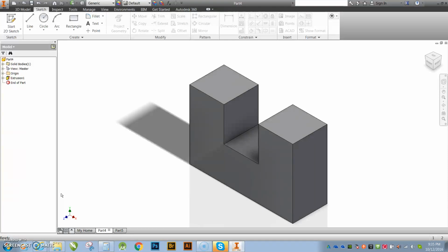And then I'm also going to talk to you guys about the additive and the subtractive method, along with the line and sketching. Neither one is better than the other. It's really preference. Once you get comfortable as far as sketching, I do believe that the line tool is one of those tools that speeds up the process and kind of helps you out a little bit. However, don't be afraid to use the additive and the subtractive method creating sketches. And I'll show you what I mean here in just a minute.